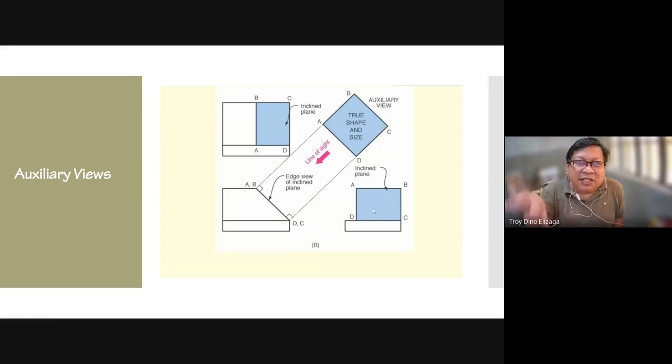So whatever is the design there is not shown in its true measurements. Therefore, we have to make this face us. So we look at an angle so that our line of sight is parallel to the perpendicular to the surface, and then we're able to draw the true shape and the true size of that surface ABCD. So that's basically the principle.